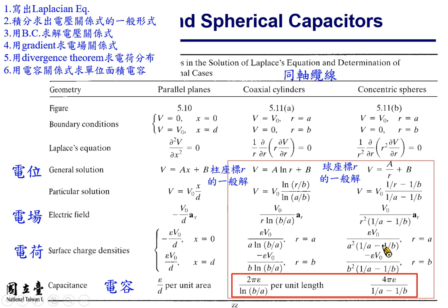You have general expression for this 1D problem in rectangular coordinate system. You apply the boundary condition, I mean the top plate voltage and bottom plate voltage. You can solve for the specific solution. You have the voltage V, and taking the gradient, you have the electrical field intensity expression. Taking the surface integral, you have the charge density and the total charge. And use the definition for capacitance, you end up with per unit area capacitance.